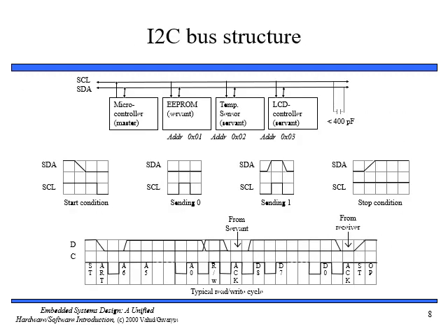So this slide basically shows a simple I2C network. The bus consists of two wires, a data wire called serial data line and a clock wire called serial clock line. The I2C specification does not limit the length of the bus wire as long as the total capacitance of the bus remains under 400 picofarad. In this example, there are four devices attached to the bus.